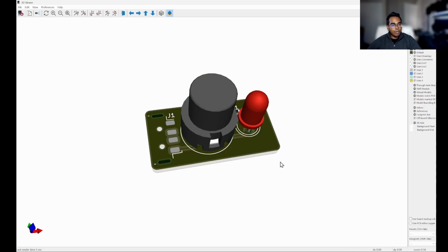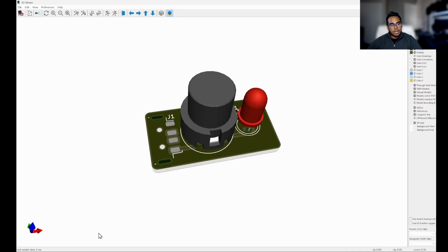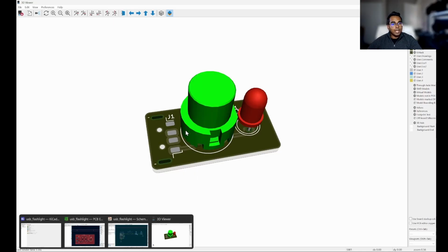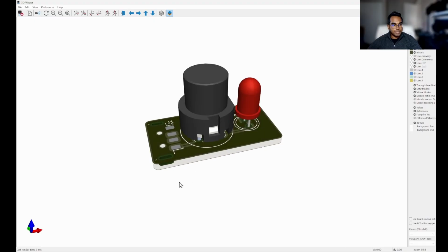So now we have all of the knowledge we need to go and find the part number for this USB connector, find it on DigiKey, download the 3D step file, and import it into KiCad so it shows up in this render. I'm actually going to do that really quick just because we now know how, and we can make this 3D render perfect for our purposes.